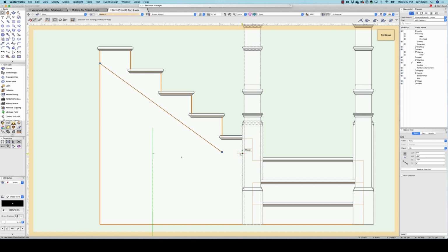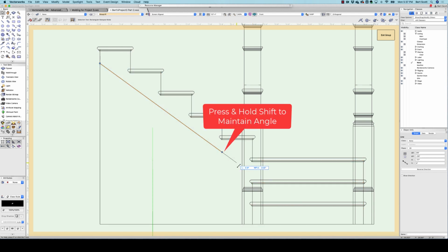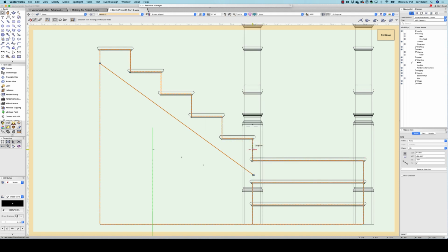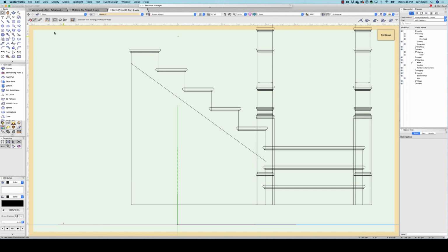going to go into wireframe for this so I can actually see the edges of things. I'm going to extend this line down to there. This is the point where the stairs switch angles. So the stairs start going up here, and then this is the landing. Now I'm going to use the 2D polygon tool to draw the shape that I'm going to subtract. So there, hold down Shift and complete it.